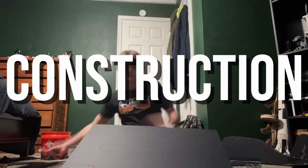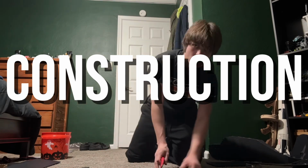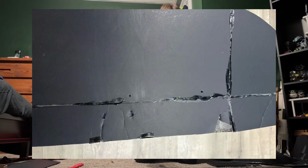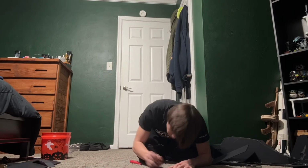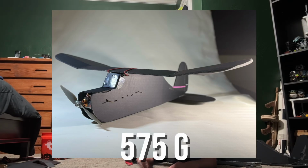We constructed the aircraft primarily from foam board because it's lightweight, easy to work with, and quick to repair. Since crashes are inevitable during flight testing, foam board allowed us to iterate without losing significant time. Structurally, the most critical areas were the wings, which define aerodynamic behavior, and the nose and power pod, which experience impacts and vibration. These areas were reinforced as needed while keeping the overall weight low. The completed aircraft had a mass of 575 grams, which served as the payload mass on race day.